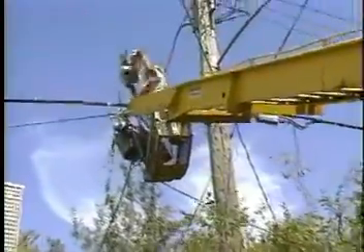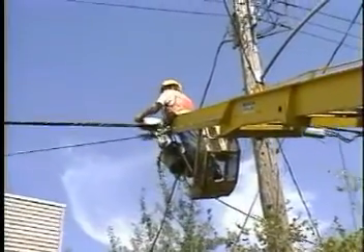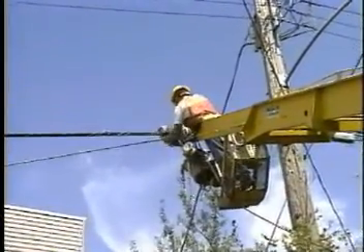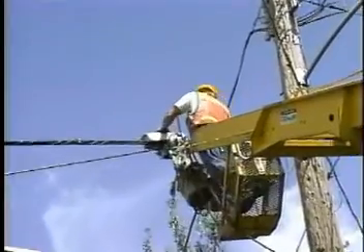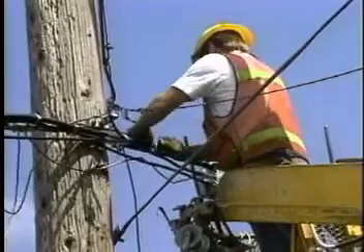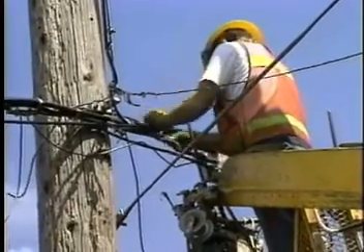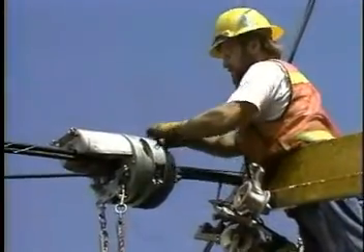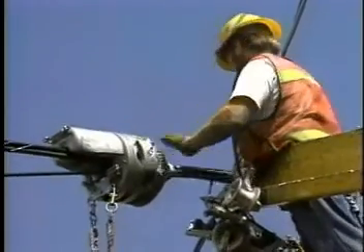At pole locations, the lasher is simply removed, passed around the pole, and reattached so the process can continue. The lashing wire is securely anchored at pole locations. When using cable lashing, the drive-off installation method tends to be faster than pull-ins.